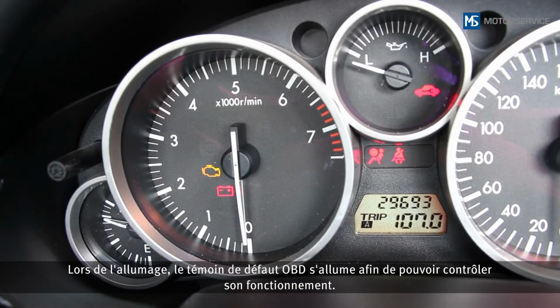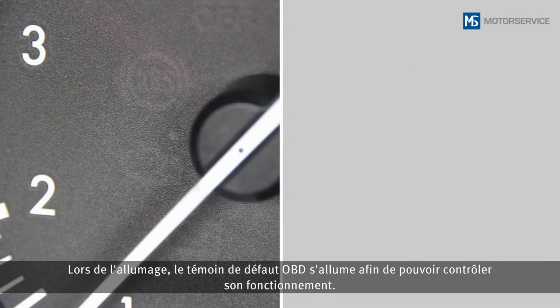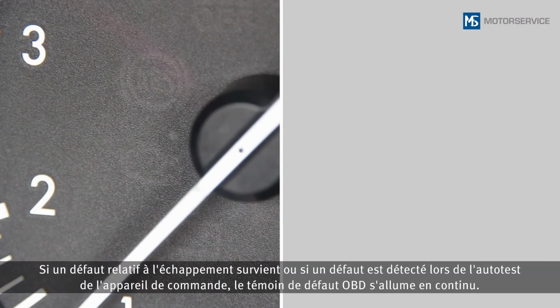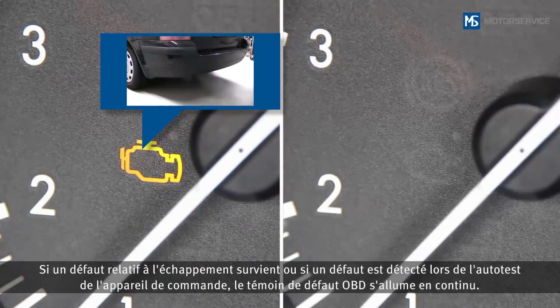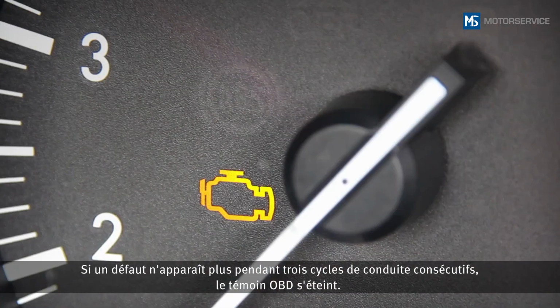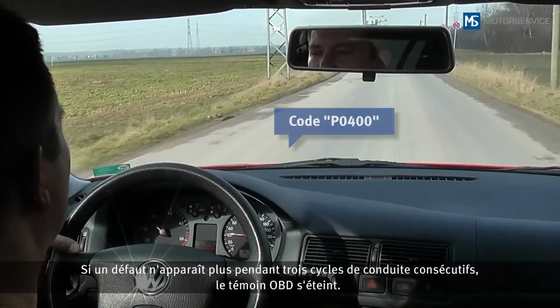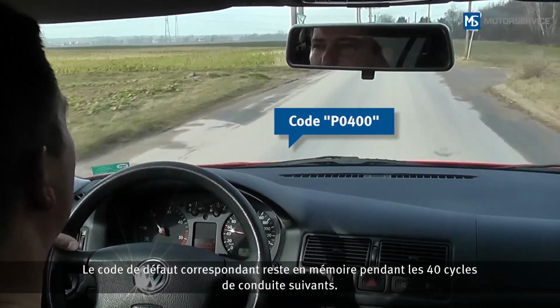When the ignition is started, the OBD malfunction indicator lamp, MIL, lights up for the function check. If an exhaust gas-related error occurs, or if an error is detected during self-testing of the control unit, the MIL lights up continuously. If an error occurs that leads to cylinder shut-off or to damage of the catalytic converter, the MIL flashes. If an error no longer occurs after 3 consecutive driving cycles, the MIL goes out. The associated error message remains saved for 40 additional driving cycles.